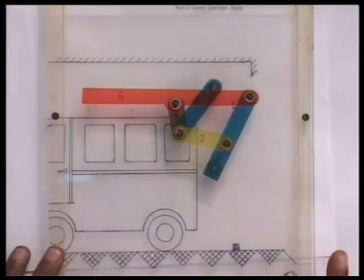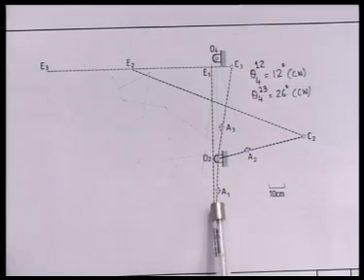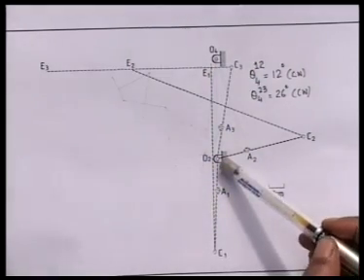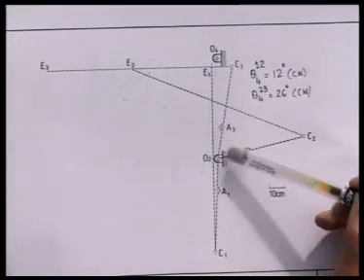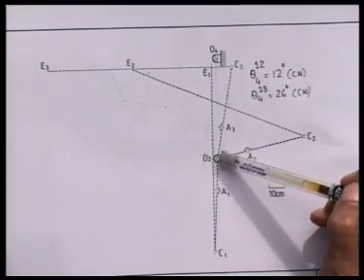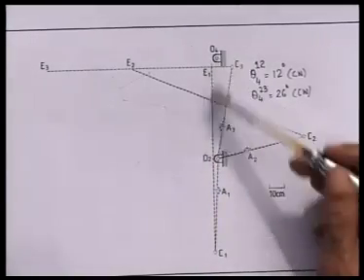And now we shall give the details of the design of this 6-link mechanism and determine all the kinematic dimensions by applying the multi-stage synthesis procedure that we have learnt earlier. So in this sketch, O2 and O4 are the locations of the two fixed hinges on the side wall. The locations of these two hinges we choose conveniently wherever it is possible.